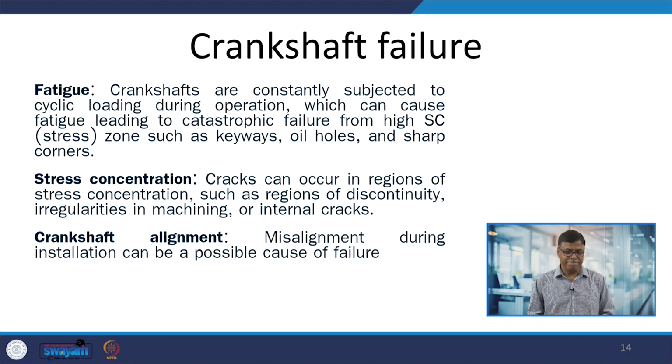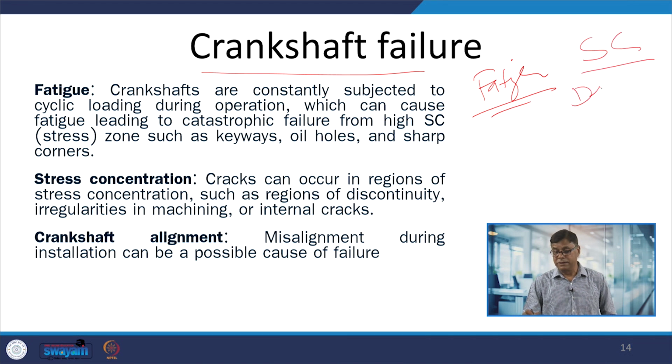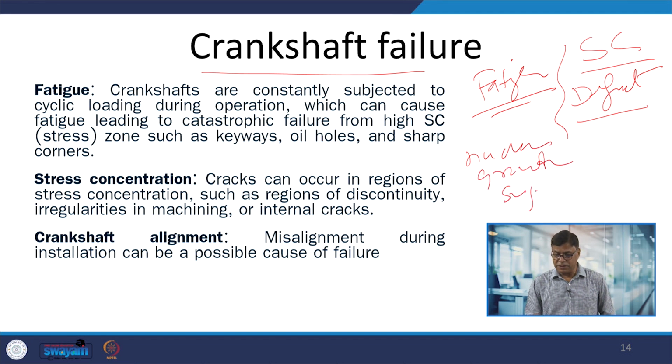Automobile is very common because this crankshaft helps in converting the reciprocating motion into rotary motion and vice versa. These are subjected to fatigue. So, for fatigue conditions, there should not be any kind of stress concentration. There should not be defects, because these will form weak zones for easy nucleation of crack, their growth, and finally sudden fracture. Okay. So, these are the three stages: nucleation, growth and sudden fracture.